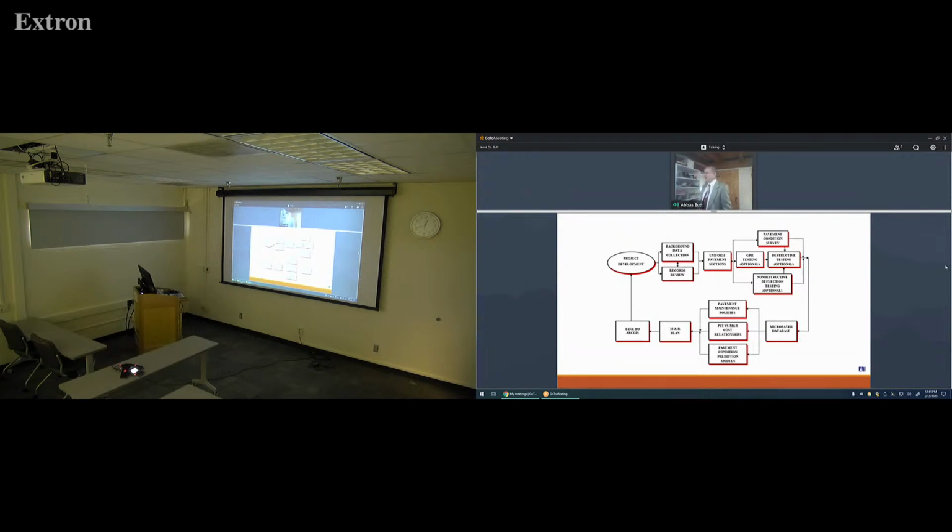Those three options were not carried out on this project. And then we did the database development, maintenance and rehabilitation policies, PCI versus pavement condition versus maintenance and rehabilitation relationship, development of pavement condition prediction models, and then the development of a maintenance and rehabilitation program for optimization of the budget or for the consequences analysis of limited budget.